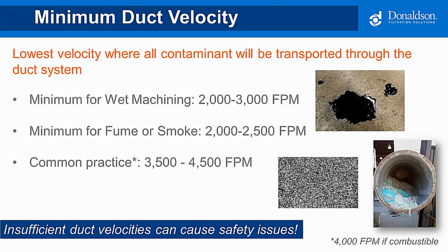Yeah, absolutely, John. You could take that approach and you may not have any issues with material settling out in your ductwork. But when you go beyond the recommended conveying velocities, you're going to require more energy to move that air through the system. Ultimately, this can impact the size and horsepower of the fan, as well as create issues such as increased noise in your ductwork, possible abrasion, and just more wear and tear with your ductwork. So you've got to be careful not to go too high in your conveying velocities and create other problems.